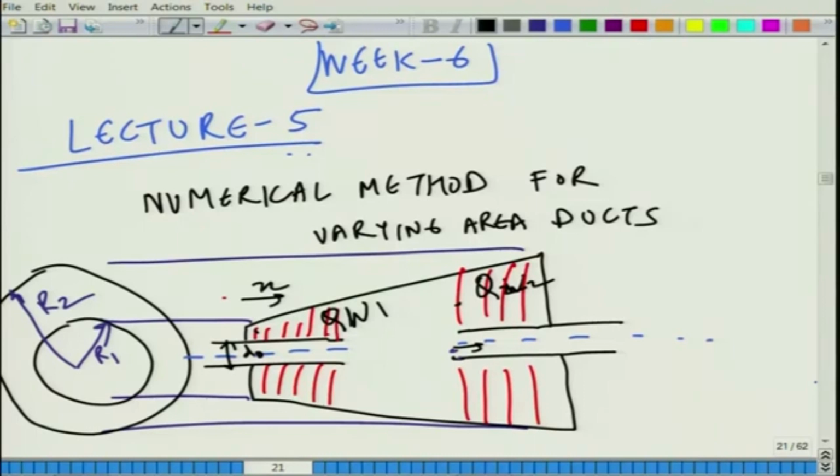what we will do in the next week, week 7, is going to be very important, where we will introduce the effects of mean flow more formally, although we have done it to a certain extent in the last few lectures of week 2, where we talked about the convective Helmholtz equation involving the convective effects of mean flow. But basically we are going to talk about aeroacoustic state variables, which involve the effect of mean flow, where Mach number M naught is much less than 1, typically 0.1, 0.15, which is what happens in automobile exhaust systems.